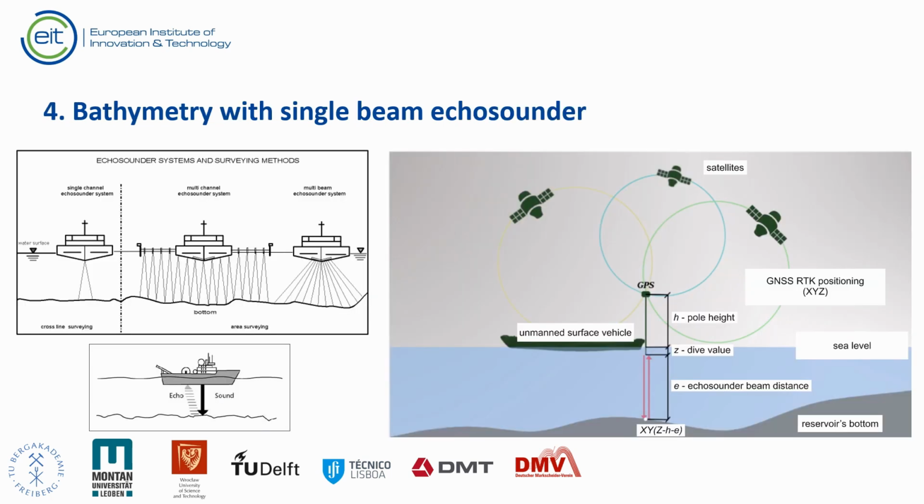The idea of bathymetric measurement is to determine the depth of the level stations relative to the water level. Classical point measurements using GPS RTK sensors for navigation and a fish finder for measuring, with the function of measuring pole height, allow mutual 3D interaction of the bottom of the water reservoir and active watercourses. Depending on the size and displacement of the unmanned vessels, its equipment is of vital importance. In particular, echo-sounder transducers of single and multi-beam type.